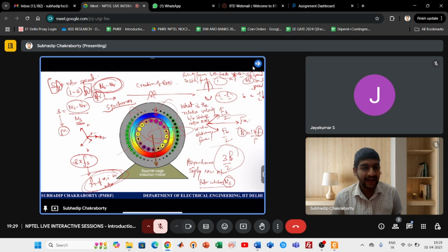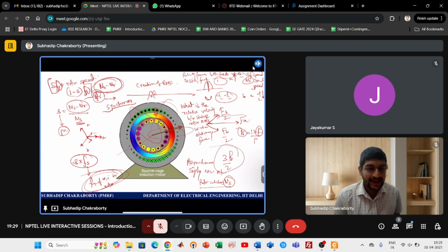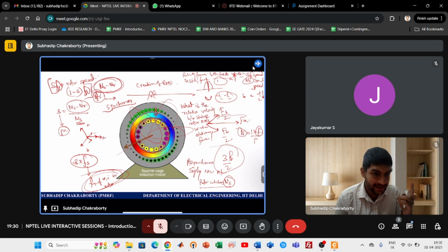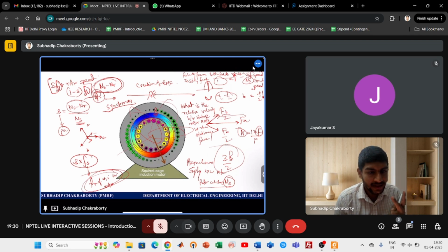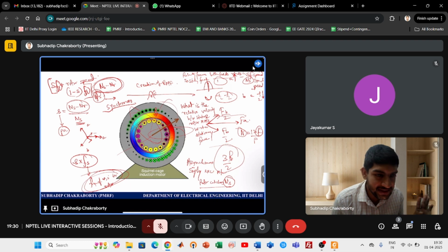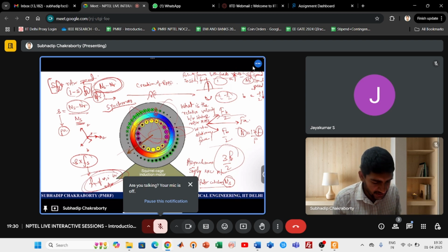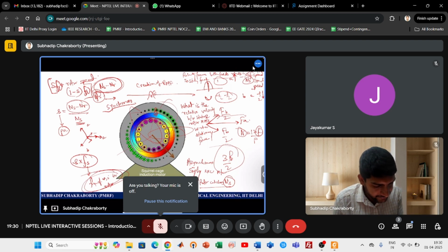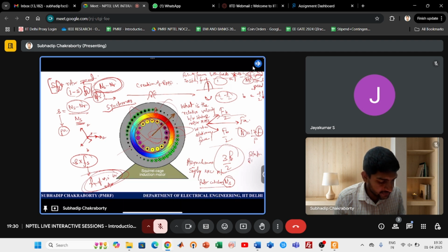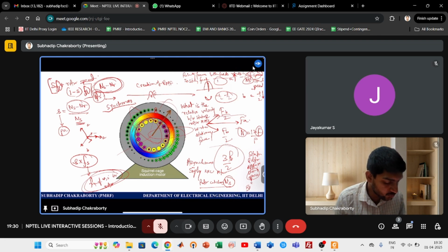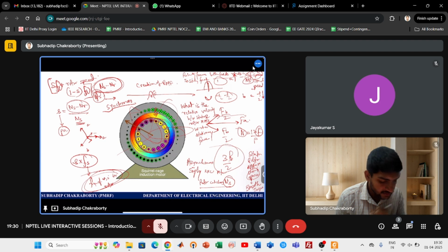So that is how we are trying to create a system which has a stator MMF and a rotor MMF. Virtually we are creating two magnets, which is essential for the rotation of any machine, and they are also stationary in space with respect to each other, which will generate smooth torque. Stator and rotor MMFs are stationary in space. Being stationary in space is a necessary requirement for rotation of any electromechanical system, for smooth torque, right?